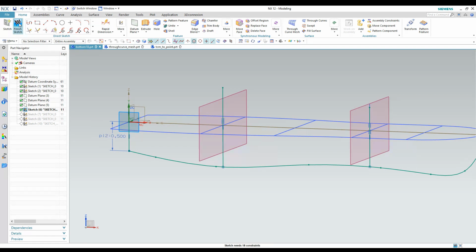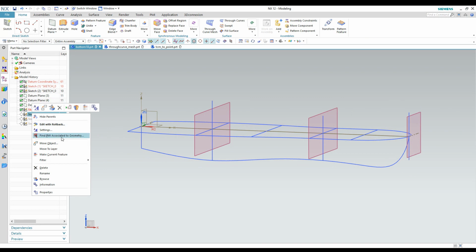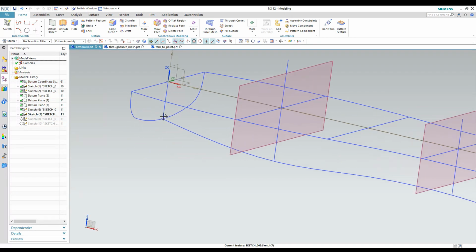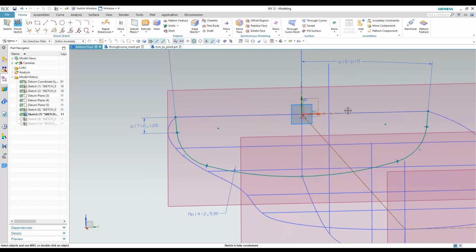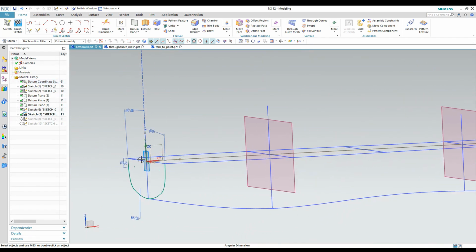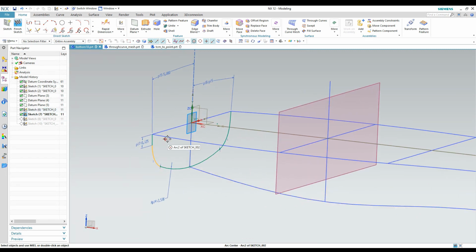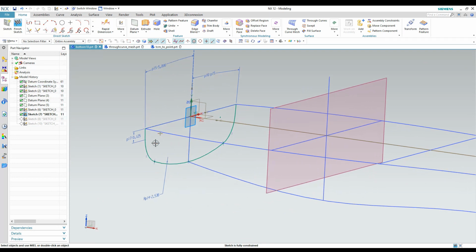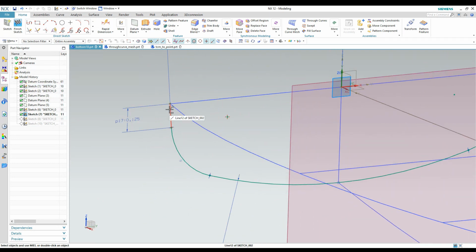Because when you're creating those sections, so let's turn on the first one here. This line is technically on the same plane as this sketch when I create a sketch at the end of this part. So is this line. The spline is not, so you will not be able to select any points off of the splines to define where this line has to come into contact.